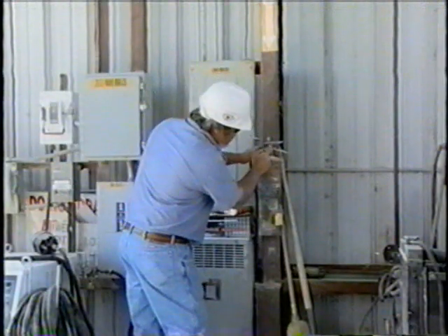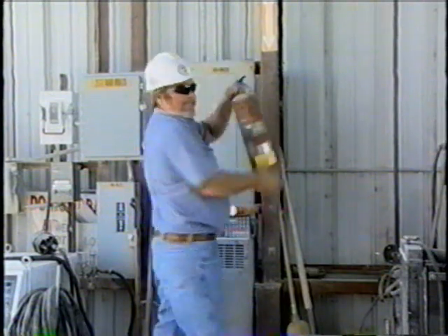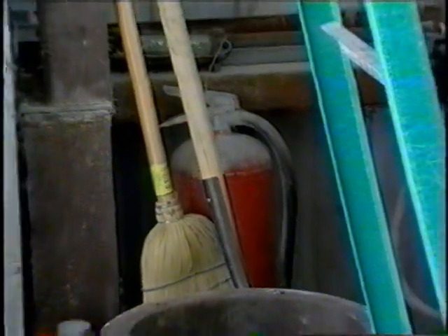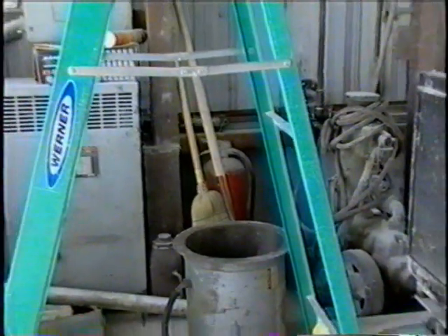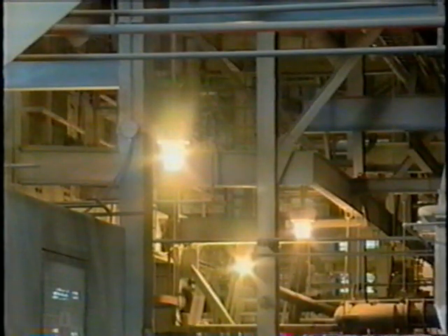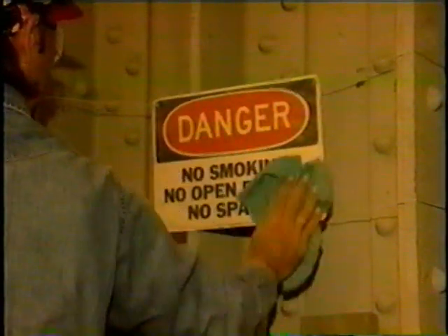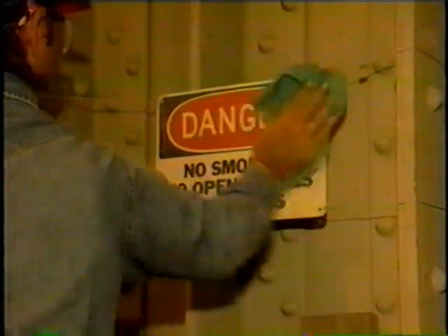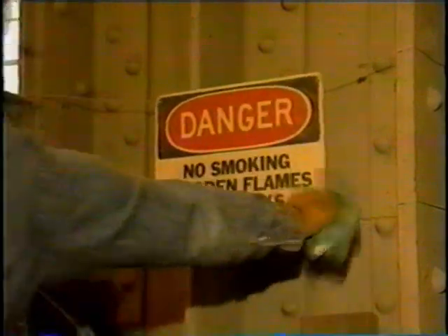A fire extinguisher that's been used and put back without proper charging is a hazard at the plant. A walkway that's blocked en route to a fire extinguisher is a hazard. Is there adequate lighting in all work areas where lighting is required? Missing no smoking signs, high voltage signs, and other safety signs can be a hazard. Deteriorated structural steel, foundations, and other plant components are hazardous and should be remedied immediately.